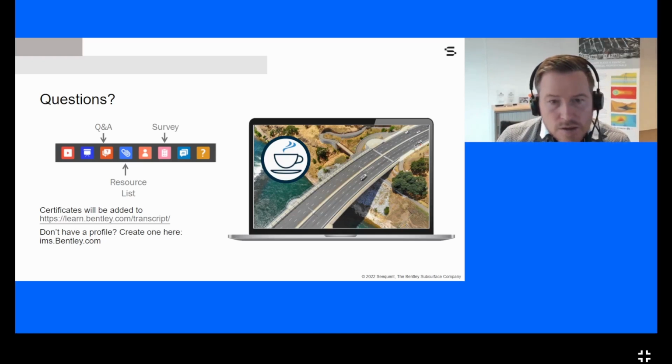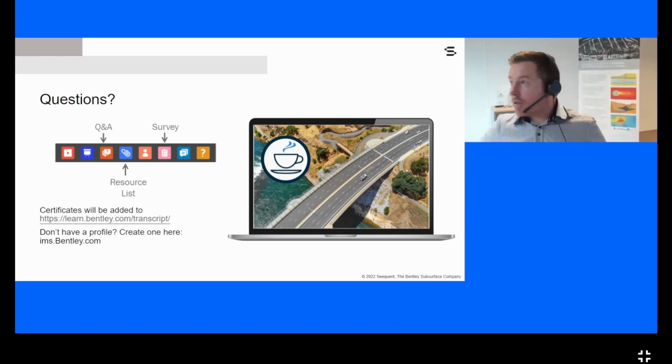Question from Homan from Afri. Does GeoStudio have an undrained soil model with anisotropic properties like NGI-ADP and PLAXIS? Yes, GeoStudio has anisotropic models, but you have to specify the directions up front. With the NGI-ADP model, which is available in PLAXIS, which has an active part, a direct shear part, and a passive part, the stress history actually determines the anisotropic behavior of the soil.